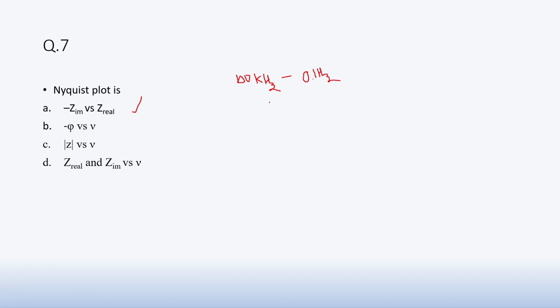In this frequency range, you are applying a sinusoidal wave with an amplitude of something like 5 millivolt. It can be as low as 5 millivolt, and sometimes you apply 10, 20, and you can also go up to 50, or even more. It all depends upon what feature you are trying to learn.